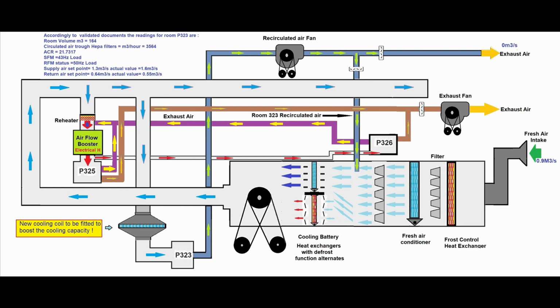The air handling unit, which uses heat exchangers that run on negative temperature, needs defrost. But if you alternate two coils which supply air for the same duct, you have to make sure the dampers are properly isolated and they can hold. Now you will see here we alternate two heat exchangers, so one goes on defrost while the other one is running